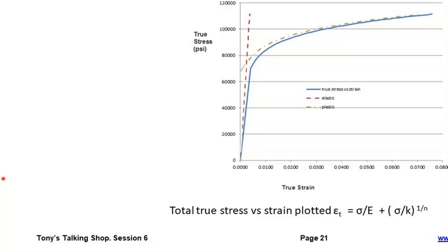And then I've taken a bit of a flyer. I've actually come up with techniques which are probably not very valid techniques, where I actually put the perturbation load and use the Neuber solution for the perturbation load. Now, there are better solutions for that. The Seeger method, which I don't have a great experience over, would be one approach we would use there.